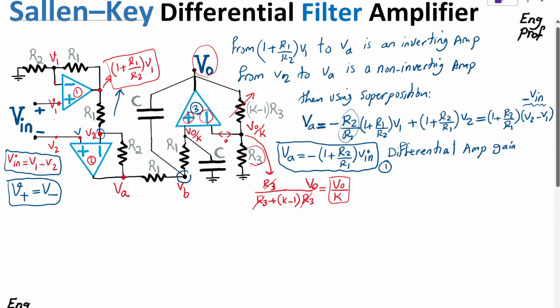Okay, so the last thing I need to do to solve the whole problem is just write one simple KCL, or Kirchhoff current law, which says the current that is flowing inward, in this case this current, which is simply VA minus VB over the resistor R1, this resistor, should be equal to the current that is flowing through R1 here, and also the current that is flowing through this gap. So that's the Kirchhoff current law. The sum of currents flowing in and out of a node in a circuit should be 0.